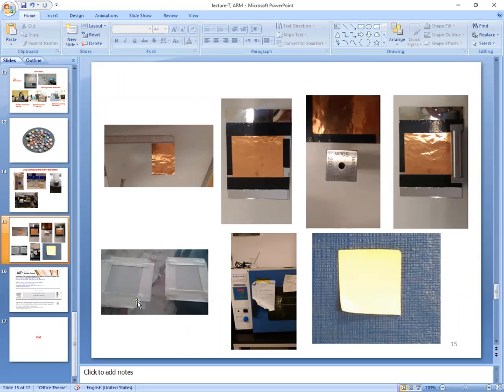You can see these are the actual images taken at Cordoba University. This is the PVC-based composite thick films. After dragging this die on the substrate with the solution on it, you have to dry it in a microwave or heat oven.